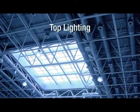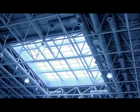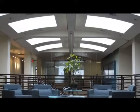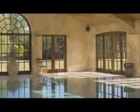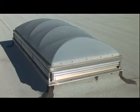Top lighting. Traditional skylights are the most common top lighting aperture. The key benefits of a top lighting system are that the design of the daylighting system can be totally independent of the building's orientation and can be designed to evenly daylight the entire floor plate located directly beneath the roof. This enables both perimeter and interior spaces to benefit from this natural light source. However, a traditional top lighting system may need between 5 to 9% of the roof area to achieve acceptable illuminance uniformity. Other challenges include the lack of easy user control of the output and the likelihood for shifting patterns of light, even with diffusing skylights.